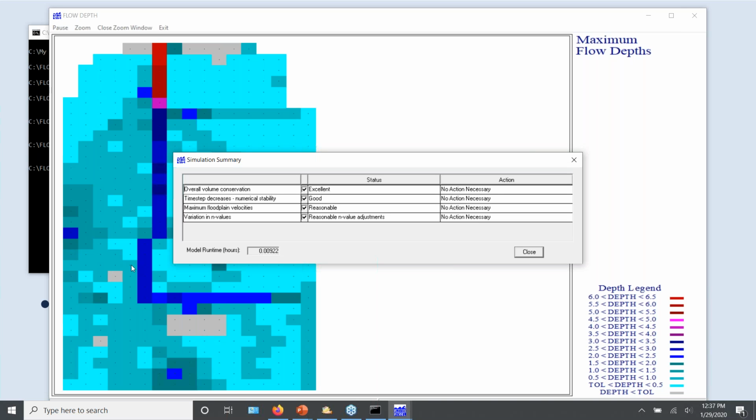And in different parts of the western United States, these alluvial fans may be on the west side or the east side of the valley. So there may be a timing issue of the storm as it moves across the valley. The storm might occur on the alluvial fan first if it's on the east side of the valley, and then move up into the upper watershed. Or if the watershed and alluvial fan is located on the west side of the valley, the storm may occur in the upper watershed first and then move down onto the alluvial fan. Those are some considerations.